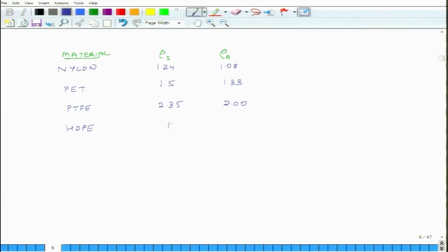The density could be as high as 1 and this could be 0.85. And similarly, you have low density polyethylene. Okay. So, you see that the semi-crystalline version is tighter, it is more compact, so its density is higher. The amorphous version has in general lesser density.